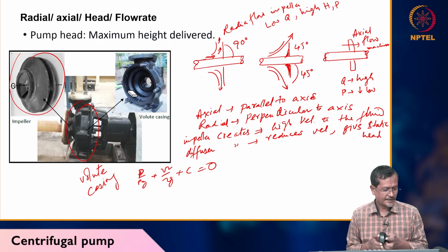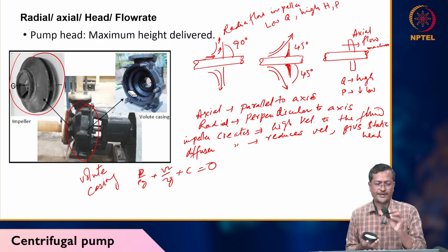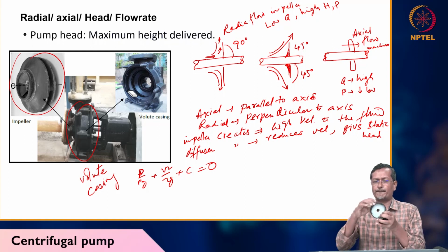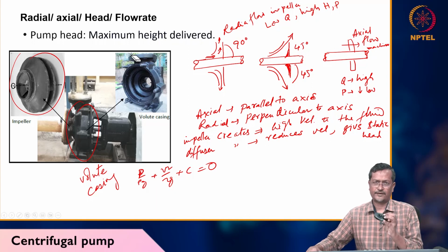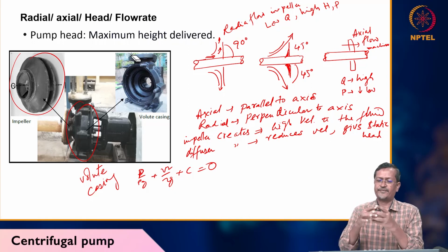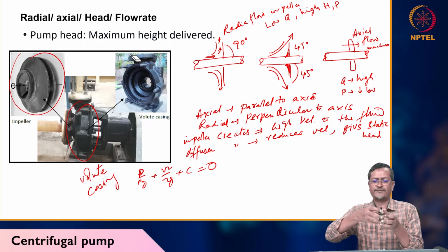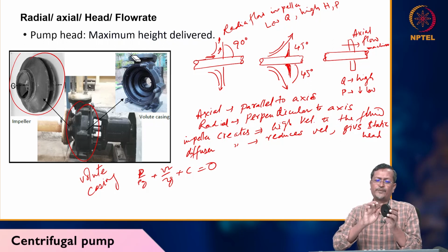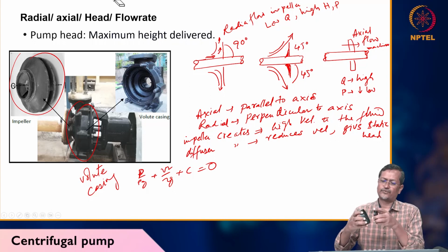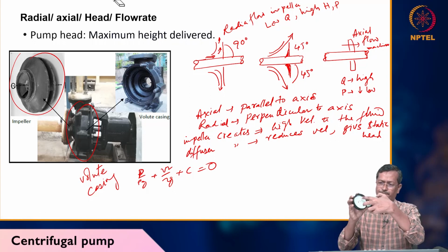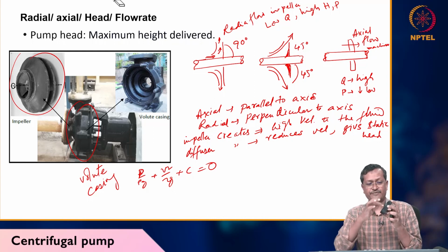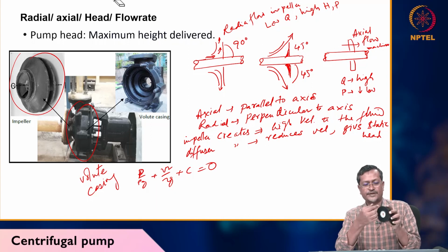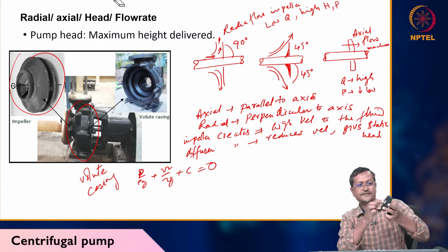So in this case, it will have one impeller. Instead of a very big diffuser, it will have a very compact diffuser. Diffuser means it will be similar to the impeller, but the opposite way, and it will be fixed here. You can see this is the impeller, and very thin narrow channels are there. When it is rotating at very high speed, maybe 3000 rpm, fluid will come out and be collected into this cavity. Then it enters this white portion, which is called the diffuser. The diffuser also has small holes, so the fluid will be collected from this side and exit from this side.